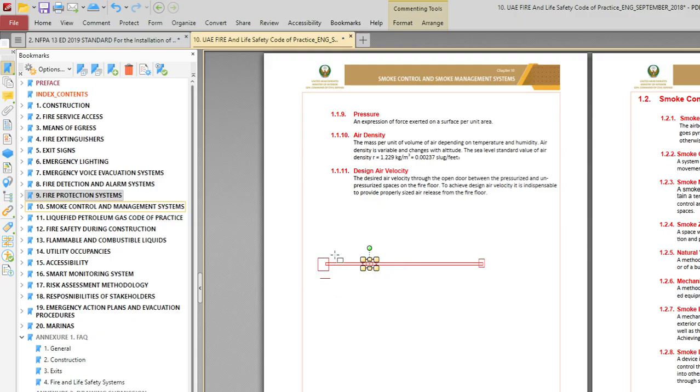Now, I'm going to design my pump for how many GPM? 225 GPM, right? But do you think the 225 GPM will reach this particular area after the pressure drop of the pipe and sprinkler? No. So that is what I'm going to calculate, the pressure drop calculation